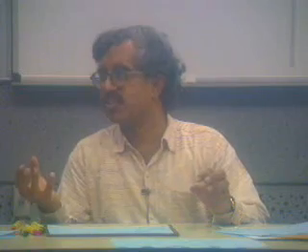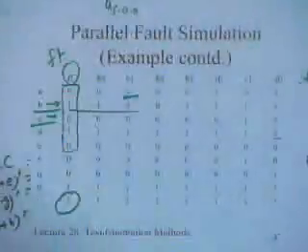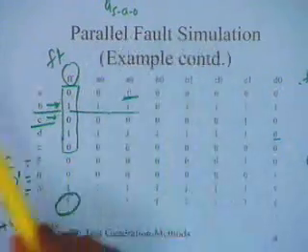And I can do my simulation in such a manner that I can fit so many faults in one evaluation. Because when you are considering a very large circuit, let's say it has 100,000 gates, and corresponding to that so many faults are there, you have to limit the number of times you need to perform that evaluation. It's going to be time consuming. And that's the reason it's called parallel fault simulation. I am simulating a number of faults in parallel. The number of faults I can simulate is restricted by the word length of the machine. Okay. So is that point clear?